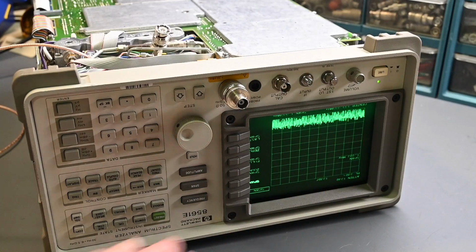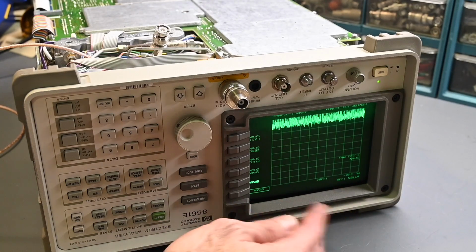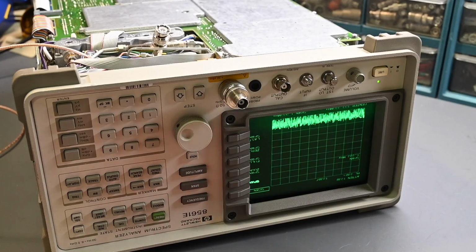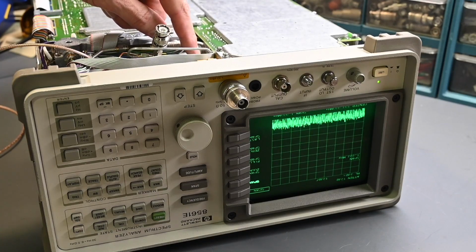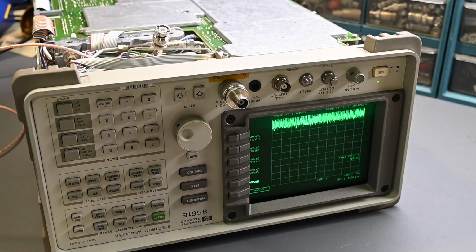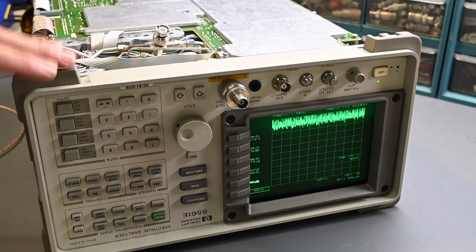Hopefully it does. If it remains constant at many different frequencies as we work higher and higher up, let's say we start at 1 megahertz and increase up to 1 gigahertz, if the displayed amplitude doesn't vary, then it really shows that the RF path and all of the components after this switch and YIG-tune filter are likely working correctly. The problem is probably at this A10 assembly. Now I still need to check the drive voltage to the switch. We'll do that after this test.